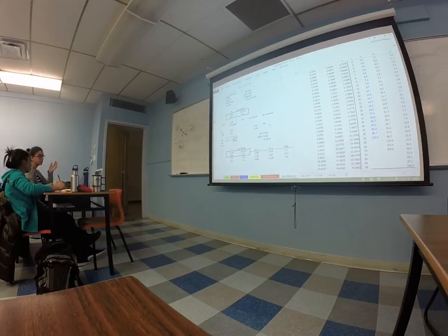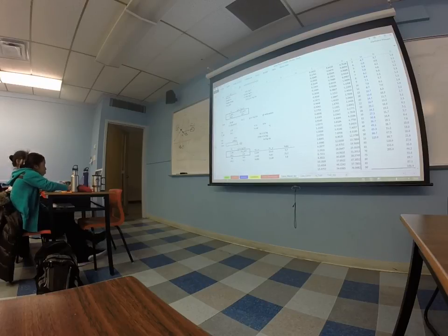We calculate first, from the dry bulb temperature, an enthalpy here. And then with that same enthalpy, we use those partial enthalpies to recalculate an estimate of the wet bulb temperature, by using the partial pressure of the water and the temperature of saturation with Antoine, like we did yesterday.